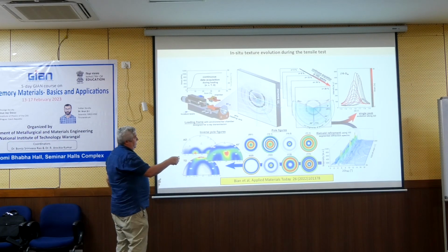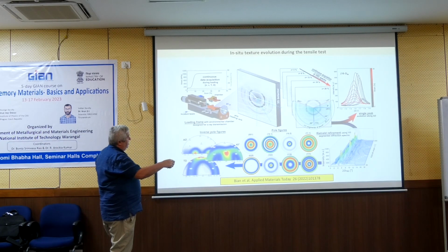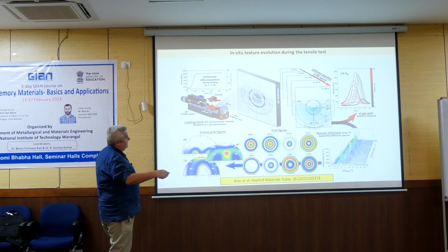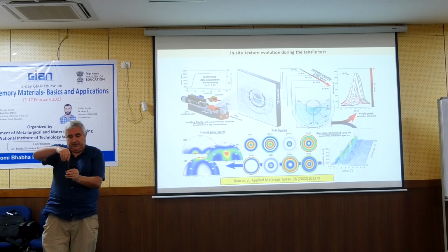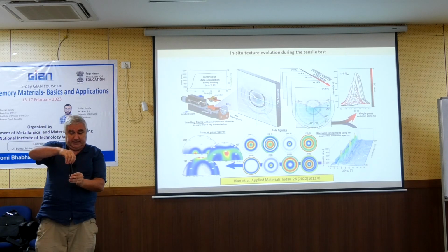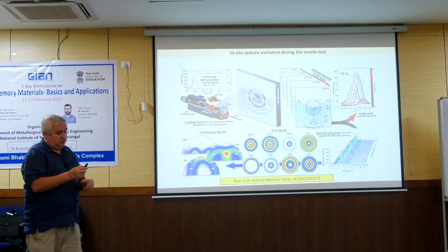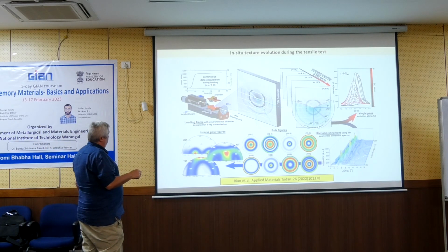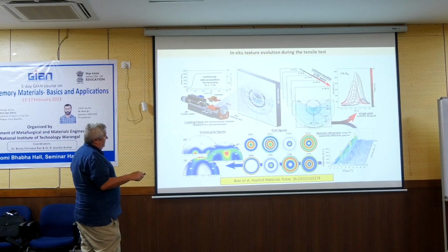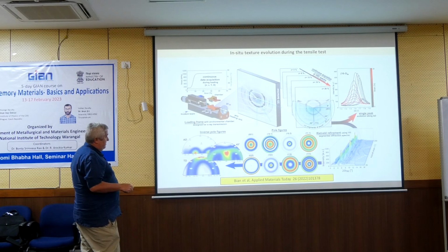So if we have such information about the diffracted intensity under different angles, and we assume that it's a polycrystalline wire, that the texture is rotationally symmetric, we can reasonably assume this. Under such conditions, we can analyze this information to obtain pole figures.